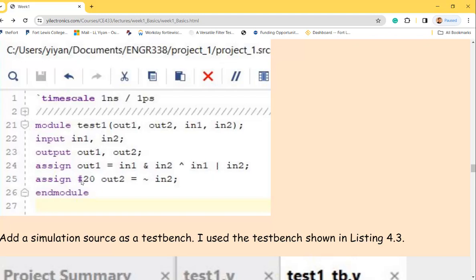Well, just because Ryan, lower down in the assignment, you have that chart you drew out of timing. Yeah. So there are 2 ways of assigning the variable, one with the little pipe headers so they occur sequentially. But wouldn't this one run the assignment of out 1 line and then after that finish? No, they do it at the same time. Oh, I thought that was with the other. That's not blocking and non-blocking, it's just assign, it's not in the behavioral. So the blocking and non-blocking only happens in behavioral.